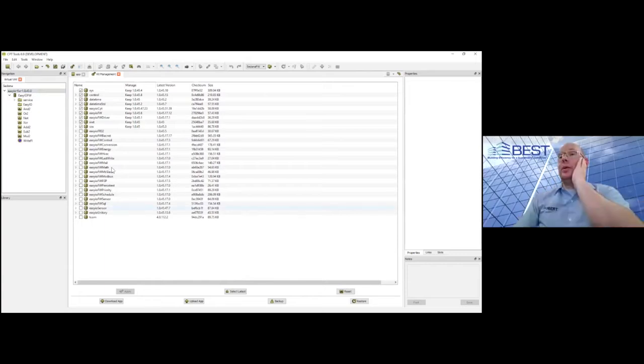Contemporary Controls, or some other company. The ones that do not have a manufacturer's name, it means that they were written as the core code for Sedona, or written by the company who originally made it, Tritium. But Tritium, I think, only ever wrote one non-core kit. But down here on my EasyIO FW Math, I'm just going to hit the check mark to tell it to install, and it's going to tell me what version it's going to install. And I'm going to hit apply down at the bottom.